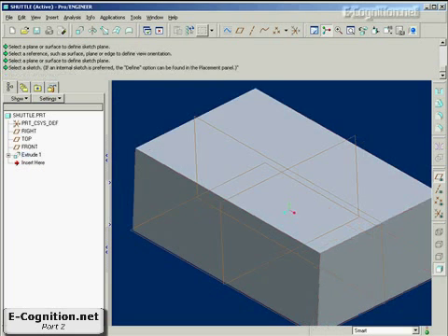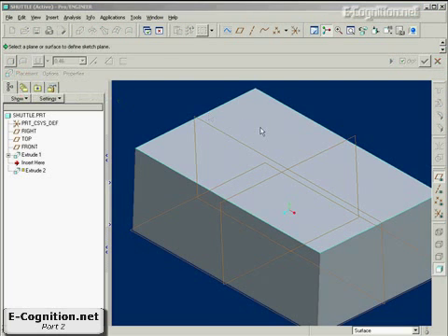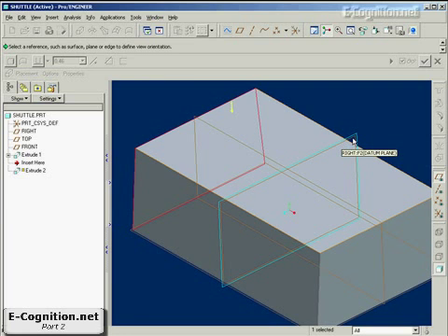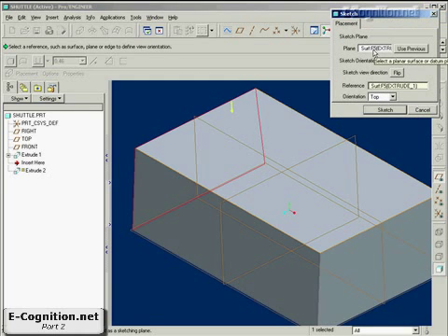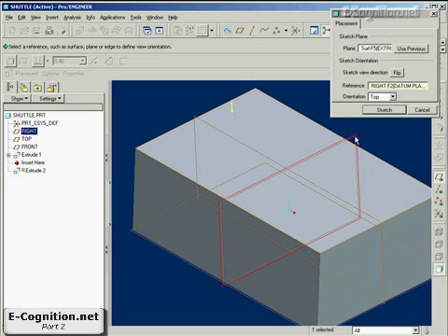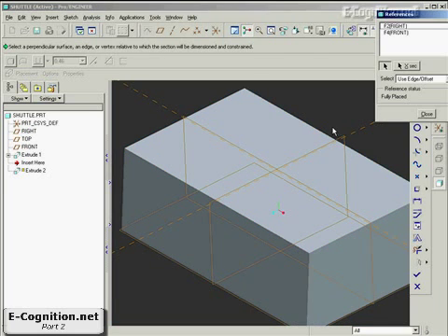Pretty straightforward. Now I want there to be a pin sticking out of the top of this shuttle, so I'll make a protrusion. Placement is going to be off the top face with, let's use this as the reference. You see how it's, here, check this out. You see I picked the face, surface of feature 5, and because I picked the face, it thinks the reference ought to be the end. That's the current yellow or highlighted collector. If I choose this instead, it will be the right plane. When I go to the sketch plane then, it also will choose that as the reference. And you'll see it's got the center datum plane as well, which is perfect for me.